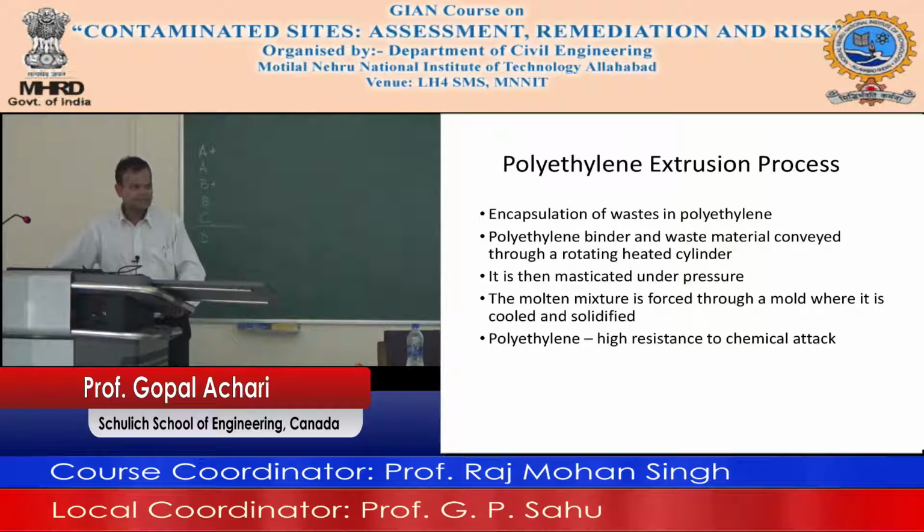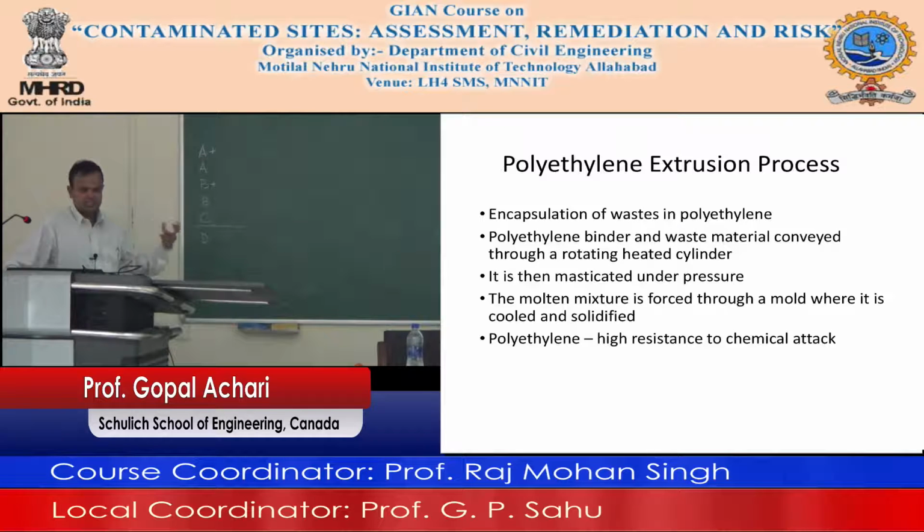So there's a whole bunch of different things we can do to solidify and stabilize a waste. If it's just paint based, a very thin material, we can use asphalt emulsion. If it is a hazardous material, then depending on the level of hazard, we can do bitumenization.